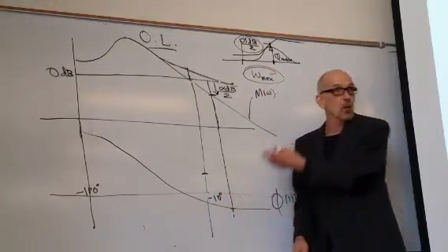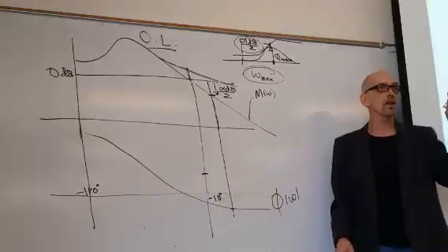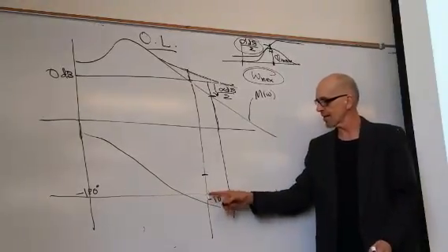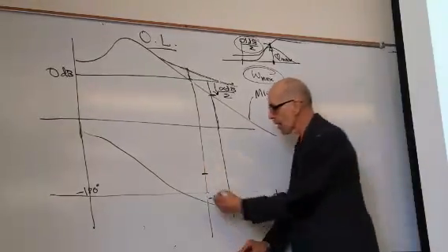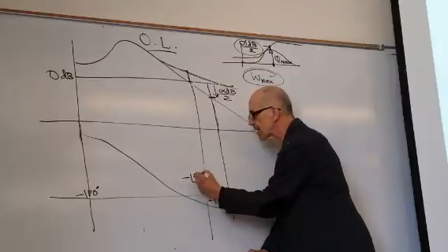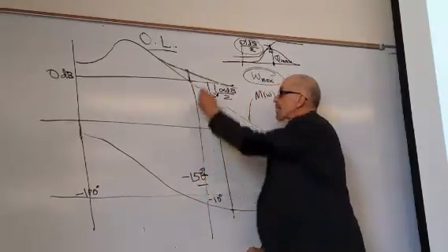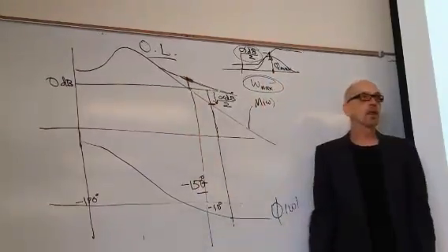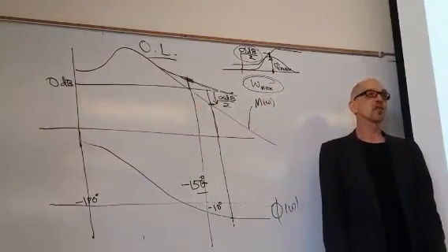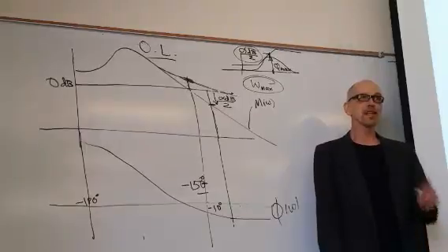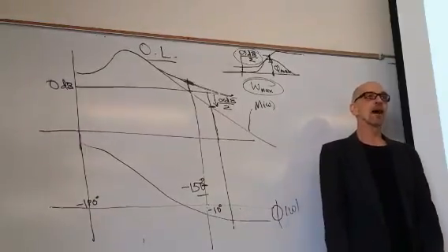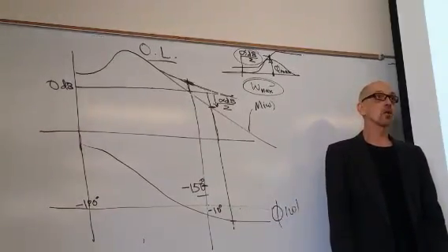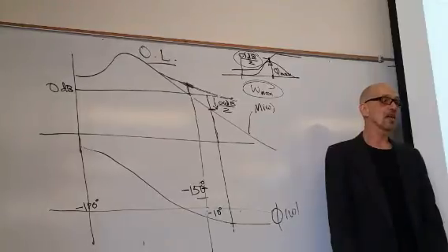Because that's exactly where you're putting it. You've got 40 degrees on the compensator, it's minus 10 here. You're going to get negative 150 degrees here. Everything's fine except this thing is up alpha dB over 2. Now design a second compensator, unity static gain, that will knock that thing down to 0 dB without changing the phase.